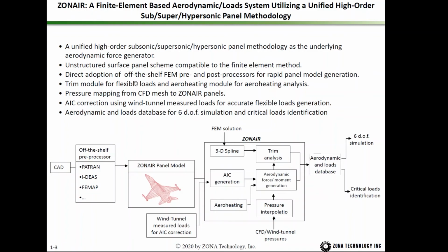It uses an unstructured surface panel scheme compatible to the finite element method. Therefore, one can use the off-the-shelf finite element method pre- and post-processors for panel model generation. And it has a trim module for flexible loads calculation and the aeroheating module for aeroheating analysis.